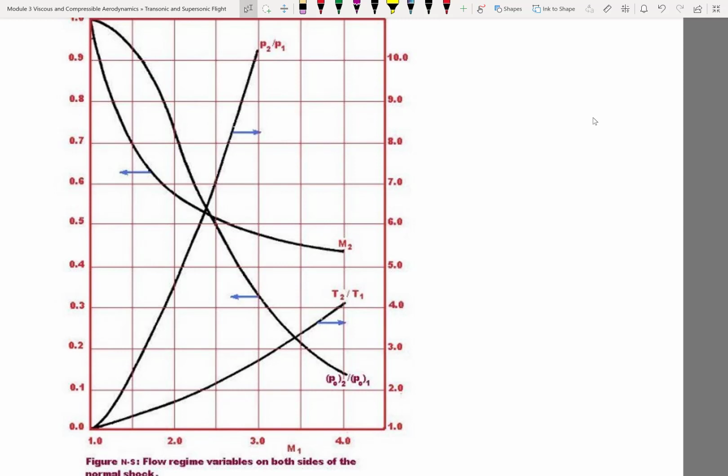As I said, the conservation of energy equation is exactly the same between these two cases. So stagnation temperature, which relates to how much temperature is there at the end of the deceleration to almost 0 velocity, is the same because at that point, all the energy is actually in the internal energy, right? So that's basically how the stagnation temperature is defined.